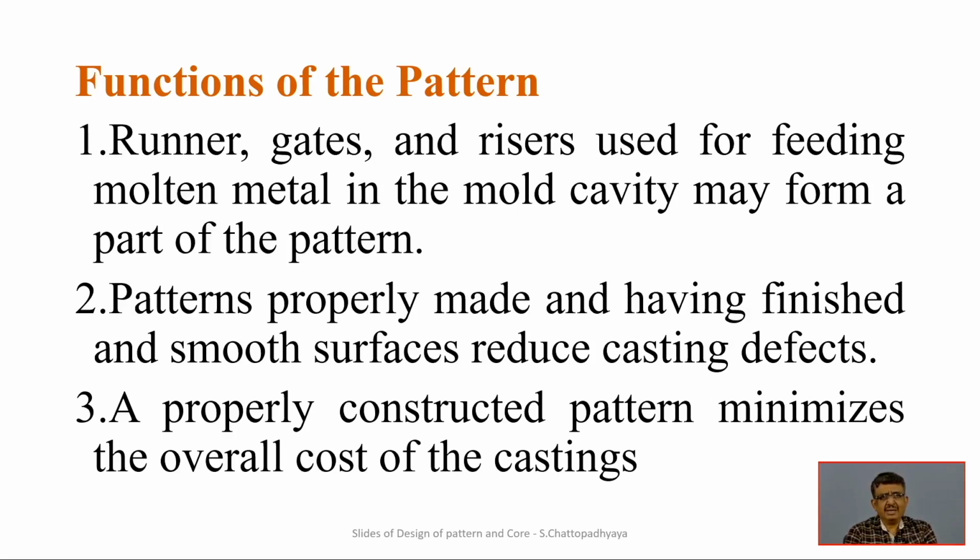And the runner and the gates and the risers used for feeding molten metal into the mold cavity may form a part of the pattern, because the pattern will also make all those things, the preparation of the runner and the risers. So those things are also made by the wooden pattern, though they are not part of the exact part of the casting, but they are necessary supporting accessories related to the casting process, and they are also made by the pattern.